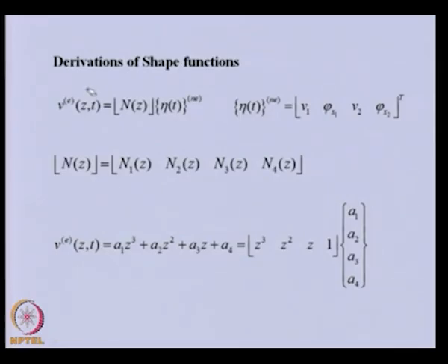So as we have chosen the shape function as an approximation, and we had the nodal displacements in the element as these 4, because there is a 4 degree of freedom element for two nodes, we expect there will be 4 shape functions. As we have seen in the previous condition, a cubic polynomial is sufficient to represent the shape function for this particular problem.